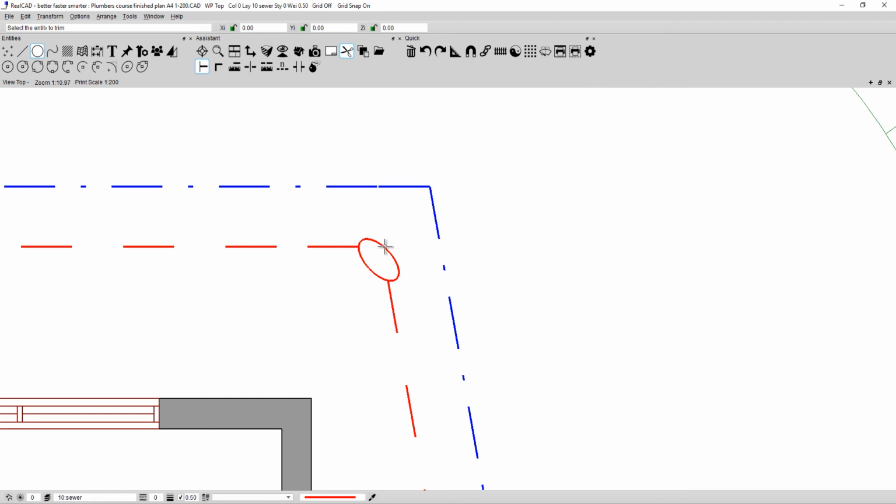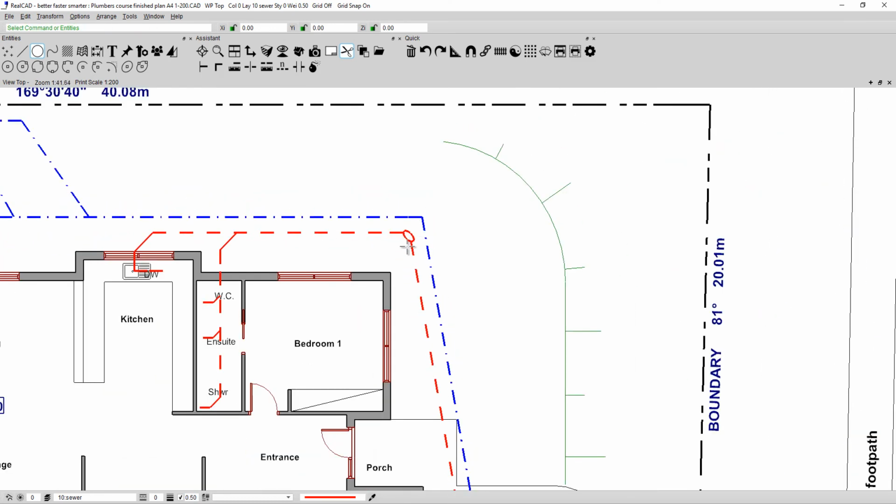You can obviously move the ellipse around. It doesn't have to be in the same location. You've got the ability to move it and retrim. Because we've got the grid switched on, we don't have a lot of freedom of movement. We've got these 100mm increments. That can be switched off, but right now it's really good just to leave it in position. So very happy with that location. That looks fine to me.